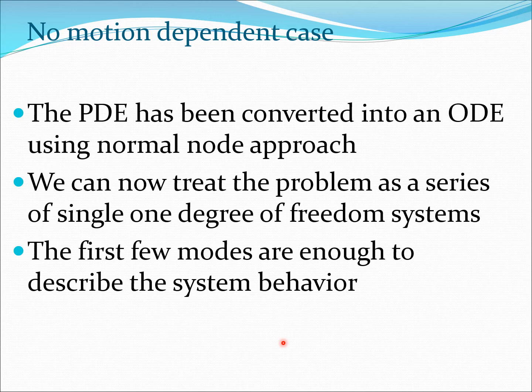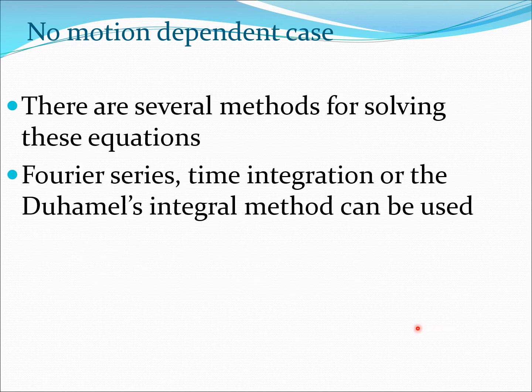Now the PDE has been converted to this ODE using normal mode approach. We can now treat the problem as a series of single 1DOF systems, and the first few modes are enough to describe the system behavior. Now there are several methods for solving these problems. There are the Fourier series method, time integration methods, Duhamel's integral method, and so on. Now, all of you who have taken courses on numerical analysis or computation know that there are established ways to solve simple ordinary differential equations, and you can solve those here. You can even use MATLAB to solve these problems.